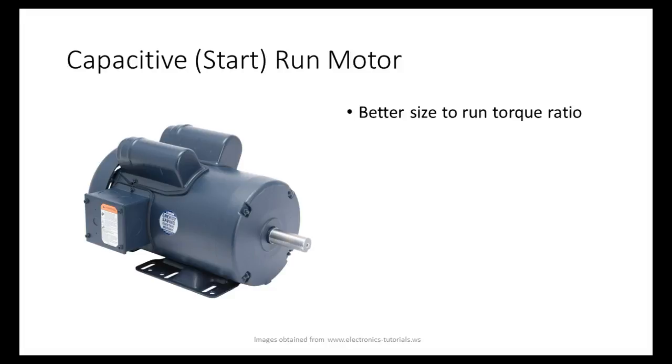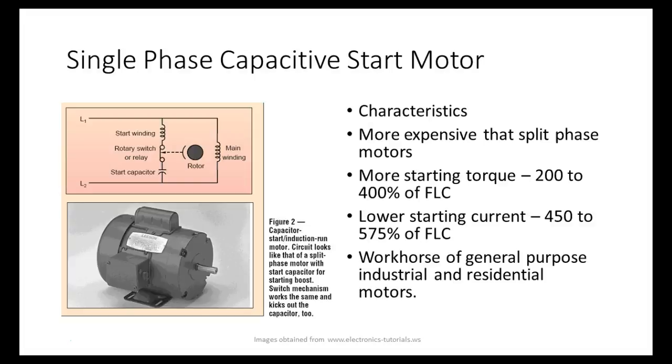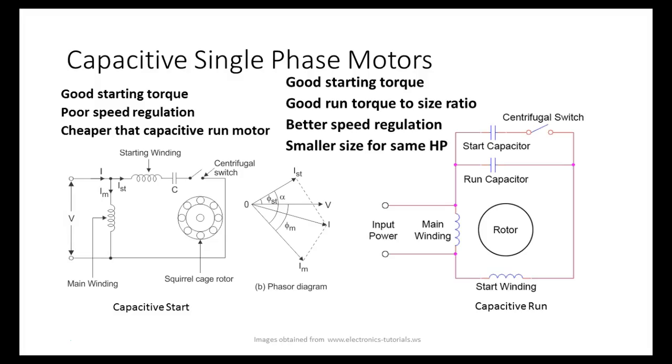So this is a dual capacitor motor. A lot of them, like I said, have the actual capacitors mounted externally. It might look like it's got one capacitor, but you look and it's got 3 wires connected to it, because your start capacitor has a common, and I can put 2 capacitors out there, right?